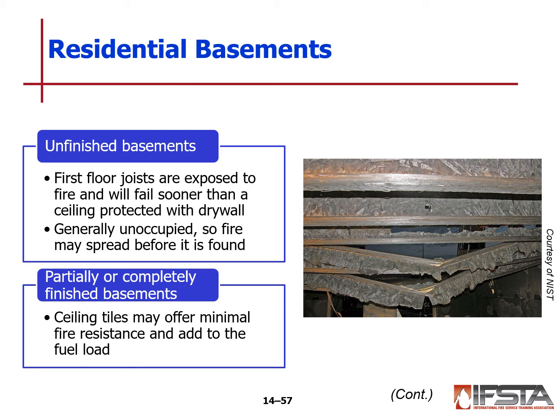I will say, in modern residential construction, the building codes have changed a little bit, and you are required to have smoke detectors above and below your stairs. So in my basement, I do have a single smoke detector at the bottom of the stairway, as well as one found at the top of the stairway, close to that opening. But we've got to realize that my house is new, and there are plenty of old houses out there that have not been retrofitted with smoke detectors in the correct places, or maybe they're battery operated only and they've not been upgraded.